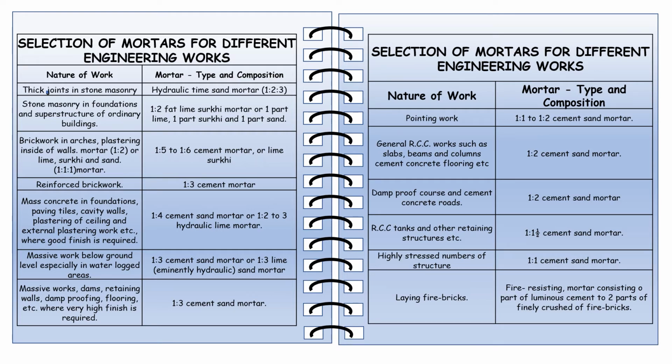Mortar 1:5 to 1:6 cement mortar or lime surki: reinforced brickwork 1:3 cement mortar, mass concrete in foundation, paving tiles, cavity walls, plastering of ceiling and external plastering work, etc., where good finish is required. 1:4 cement sand mortar or 1:2 to 3 hydraulic lime mortar: massive work below ground level, especially in waterlogged areas.